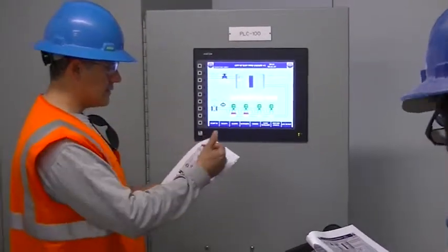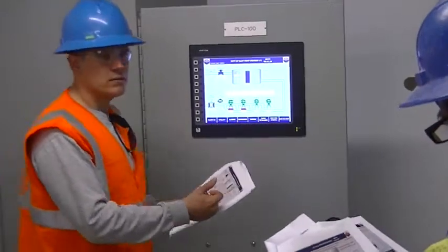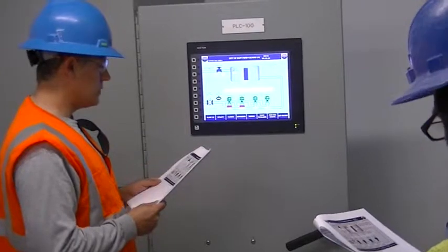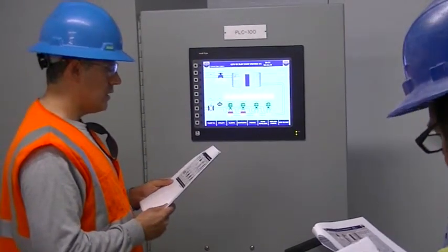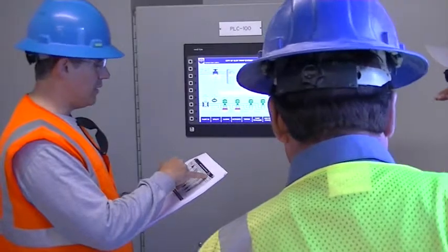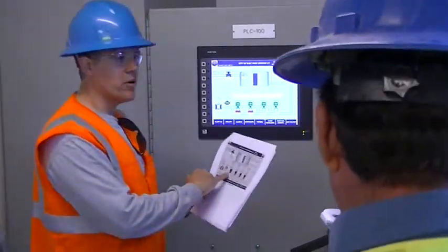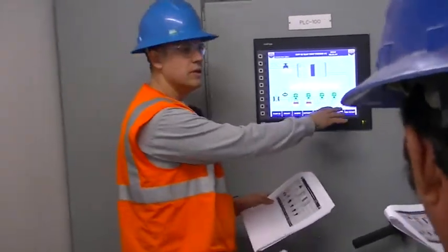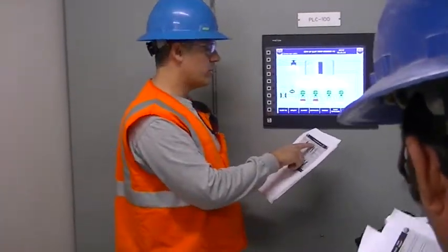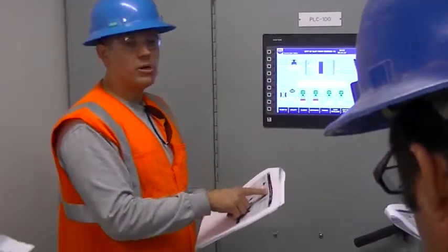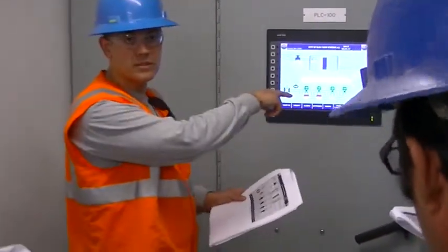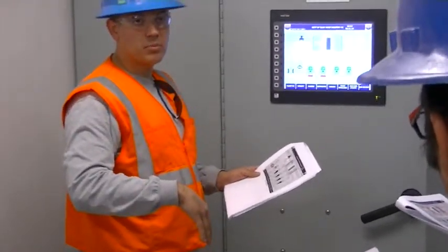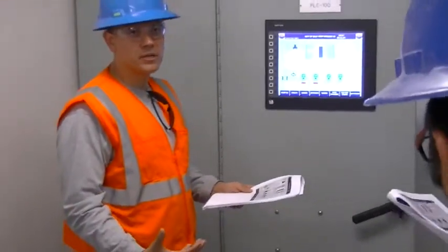Like I said, when different alarms pop up that are critical, they'll show up on this main page as well. One of the main ones is the reservoir low level alarm, all pumps locked out. Basically, that's going to turn all the pumps to an interlock. It's going to say interlock. All the pumps will turn blue, and it will flash up here. It'll say reservoir level, low switch alarm, all pumps locked out. That means the low level switch, the float in the tank, has gone below its point, and it's going to prevent any of the boosters from coming on.